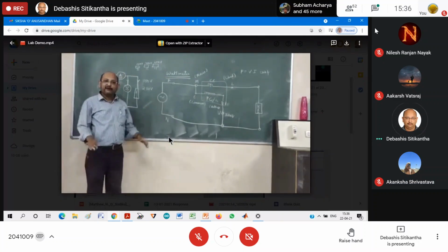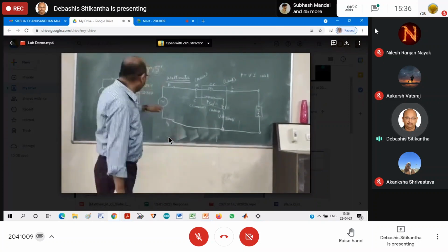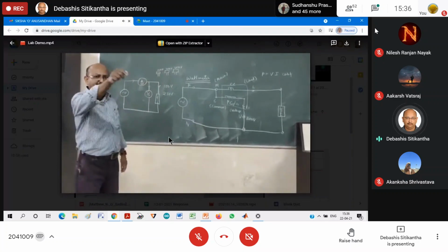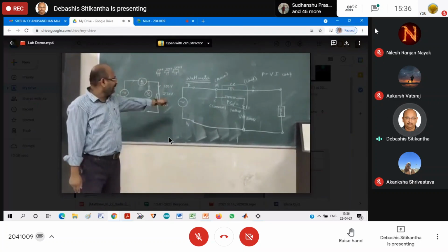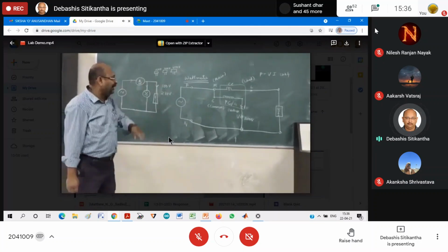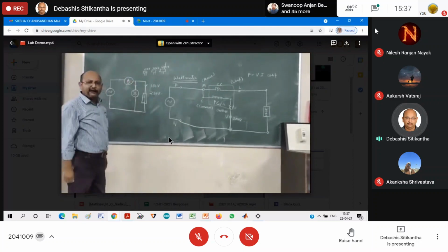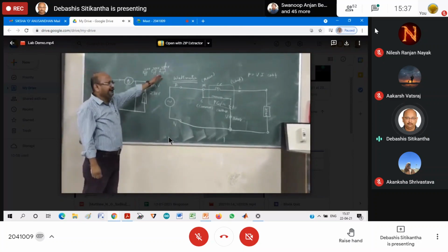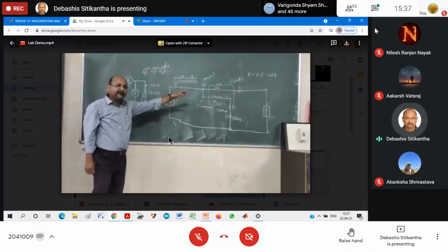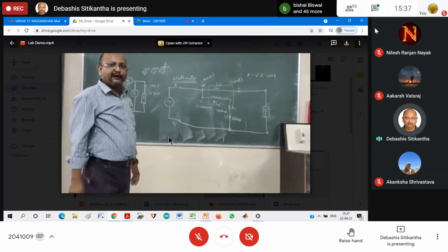Last but not least, again I will repeat the same thing that I said in the case of the ammeter and voltmeter. Suppose I don't know the voltage at which this supply is delivering the power. So what is the best thing? I will first connect it to 600. If it is not giving a proper reading, then I will reduce it to get a better resolution. So this is how the wattmeter is connected in a circuit. Hopefully you have understood it.